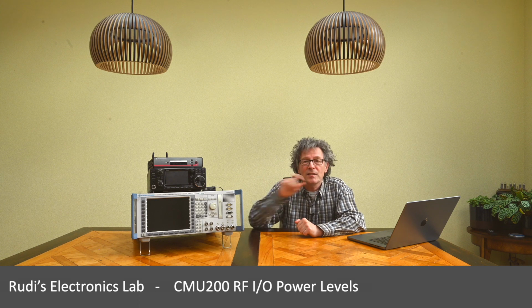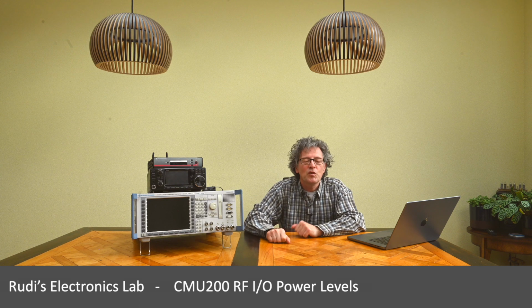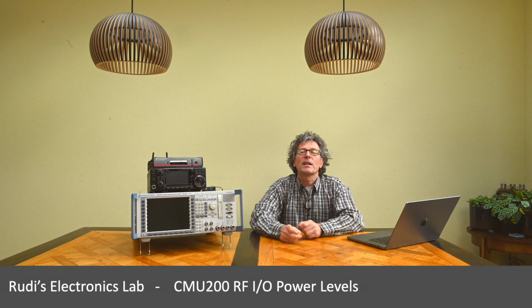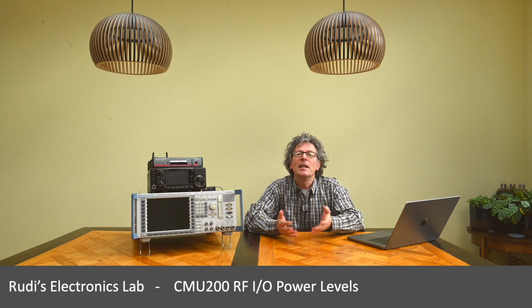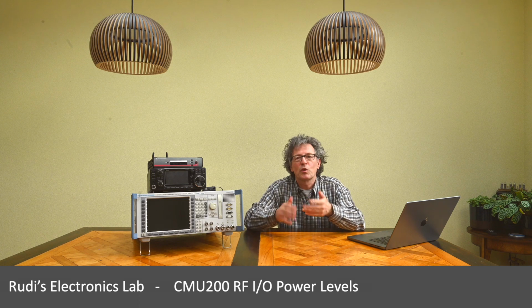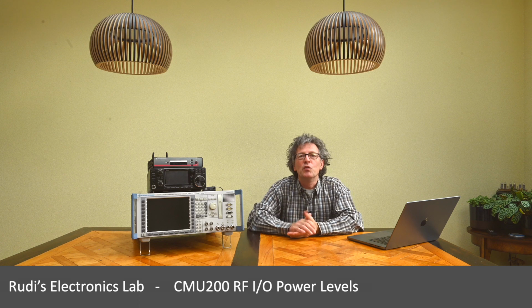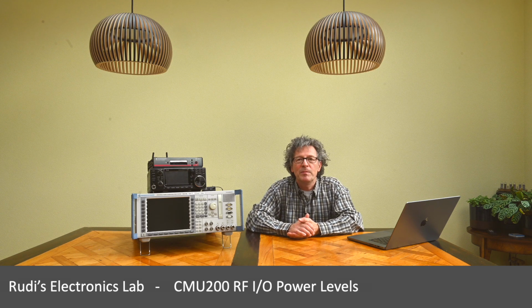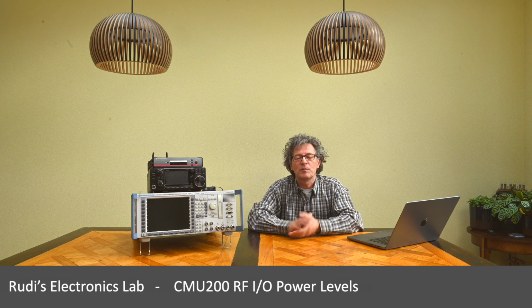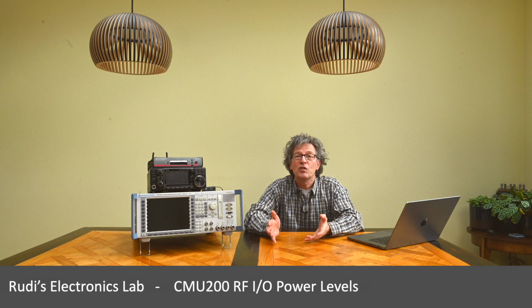And these second generators, I believe, were originally designed to deal with particular telecommunications protocols, where you might have, for example, one TDMA carrier where all the traffic was going over. But if you would use all, for example, 8 of 8 time slots in GSM, you would actually need another carrier that would carry the other type of signal, like the BCCH signal, which is more for the housekeeping type of thing. That would be the way that a regular GSM base station would be working.